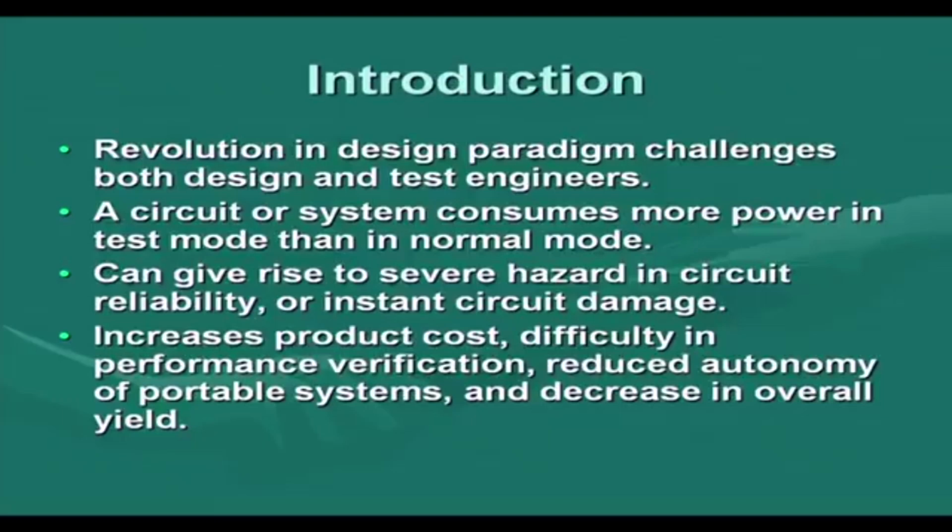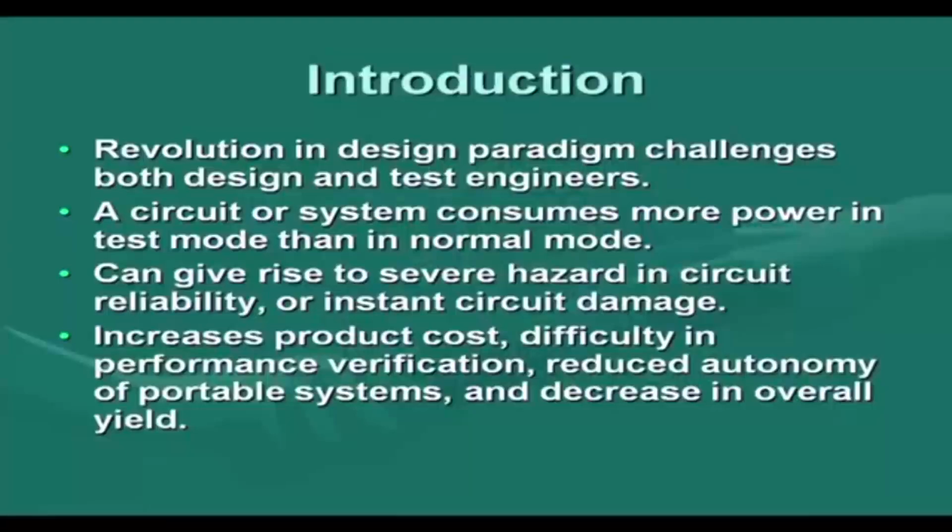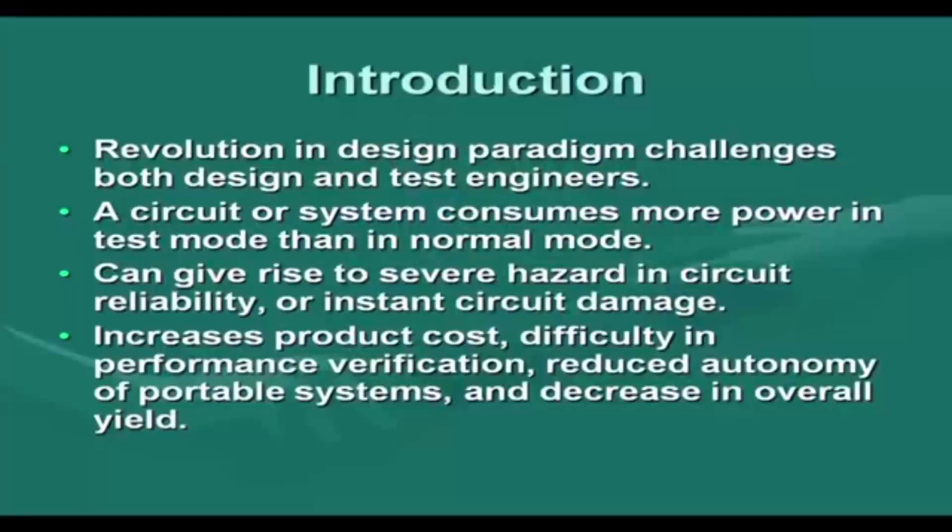Performance verification is a problem, because again the same thing, that is, this power aware operation has to come into the picture. Portability will reduce, because now the circuit has to be a battery operated circuit, if it has to be tested periodically and the test power consumption is high, then the battery life is in question. So, the autonomy of the portable system becomes less, and as a result there will be a decrease in the overall yield.